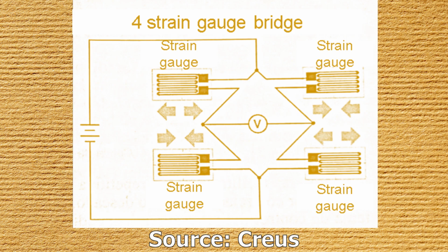The addition of a microprocessor elevates the accuracy of the circuit through the use of error correction algorithms and facilitates adjustment and calibration. The semiconductor strain gauge changes resistance with stress due to the changes in the crystal structure that vary the mobility of electrons. The gauge factor is higher than in metal gauges, being in the order of -50 to -200. The signal conditioner is also a Wheatstone bridge with the possibility of adding a microprocessor circuit.